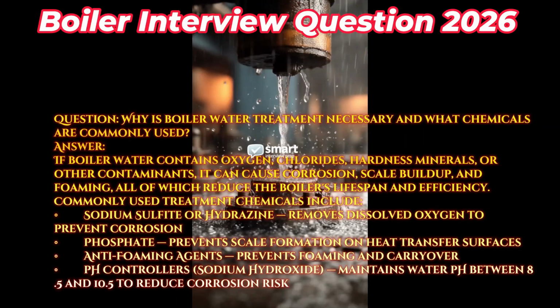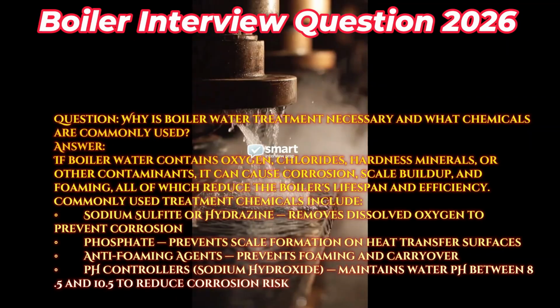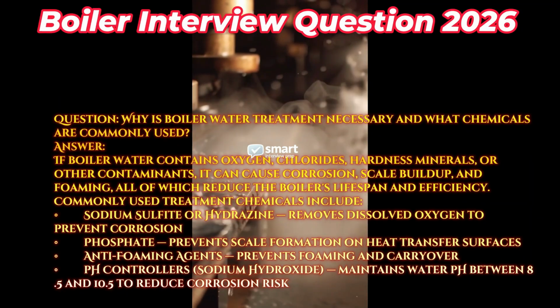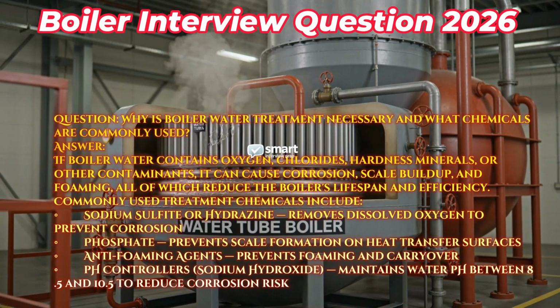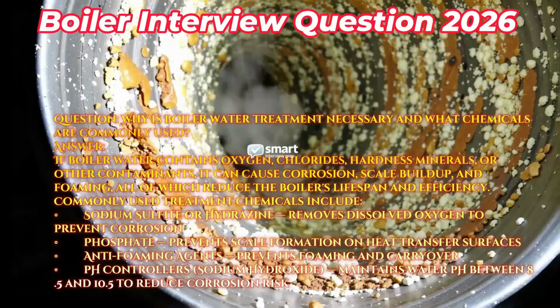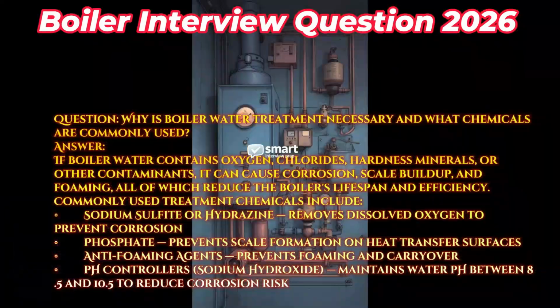Commonly used treatment chemicals include sodium sulfite or hydrazine, removes dissolved oxygen to prevent corrosion. Phosphate prevents scale formation on heat transfer surfaces. Anti-foaming agents prevent foaming and carryover. pH controllers, sodium hydroxide, maintain water pH between 8.5 and 10.5 to reduce corrosion risk.